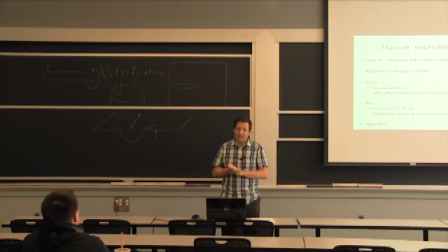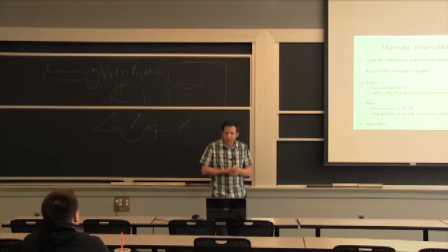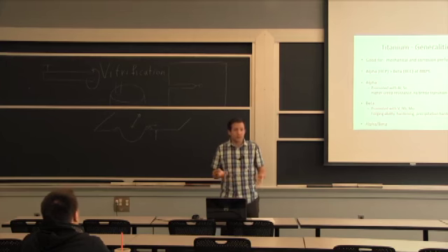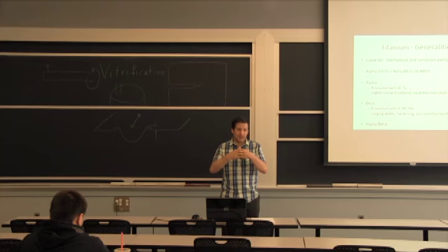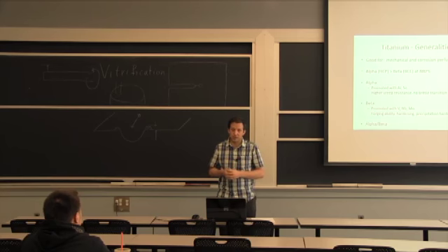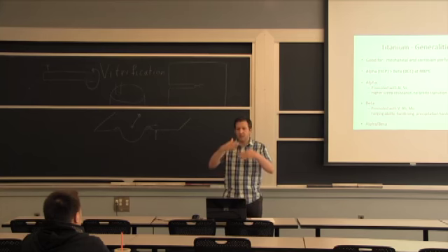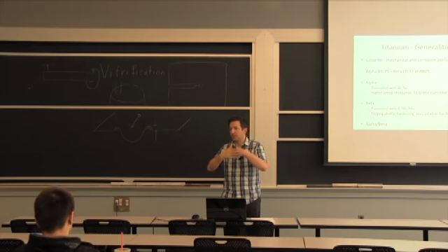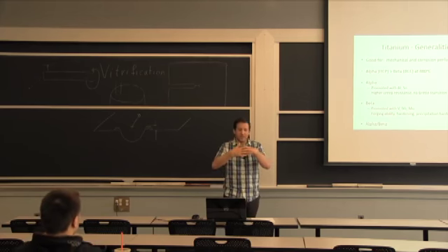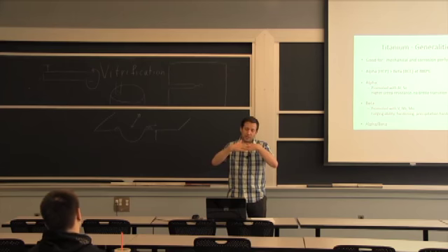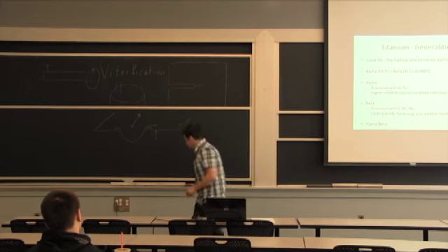If we think about stainless steel, in a lot of environments, as long as you don't have too much chloride, it's a great material. But if you put stainless steel against stainless steel in an assembly, in general, you're looking for trouble if you have movement between them. So we call it galling, because the two pieces are not really oxidized. So aluminum on aluminum is not going to stick because you have that oxide between them. But stainless steel and stainless steel, you have more sticking between the two components that are of similar chemistry, and they don't have a thick protective layer. So what happens is you adhere on one side, and then you can break the material at another location. So that way galling works.